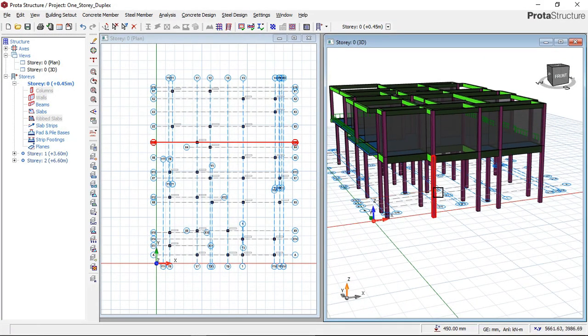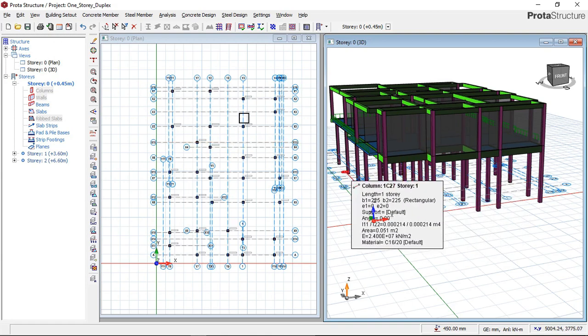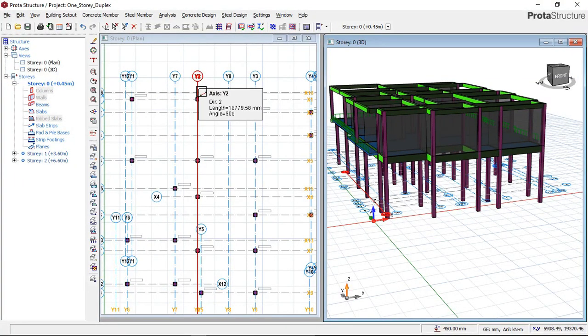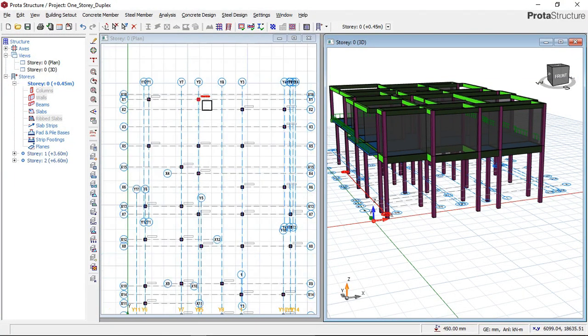So it is now your right as a structural engineer to perform the foundation design of that structure or that building, following the soil reports. Before you do your foundation design, you must have your soil properties, which is your bearing capacity. It is only from that you can be guided on the type of foundation that you will use.